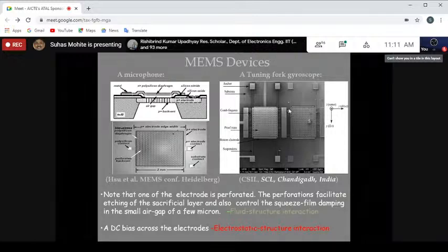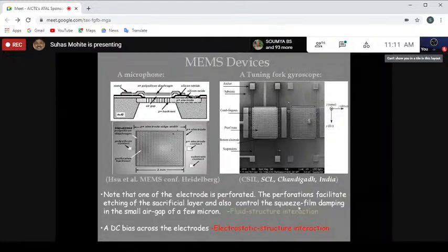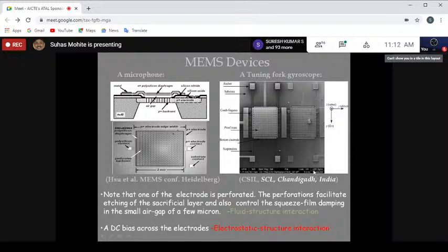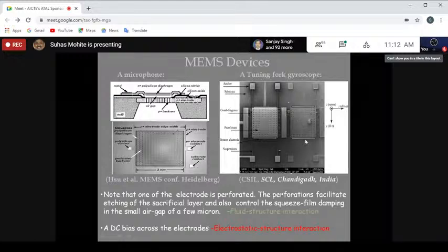So I hope you understood, and you must have got some insight about the size of the things. Now at this juncture, I will be happy to know if you understood or got some feel of the size of the micromechanical structure. This is the real structure. This is not a photo. This is a photograph of a real mechanical structure that is fabricated on a silicon wafer using polysilicon, and then the gap underneath is created by etching the material under it by sending the agents.